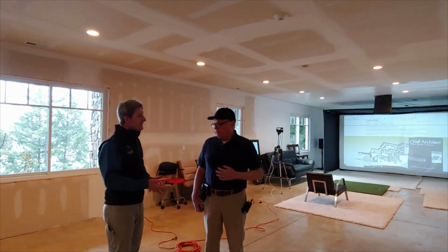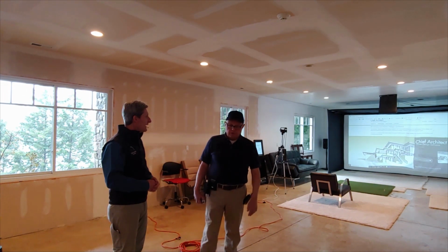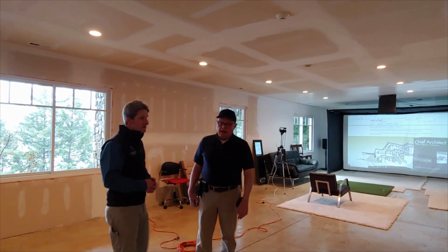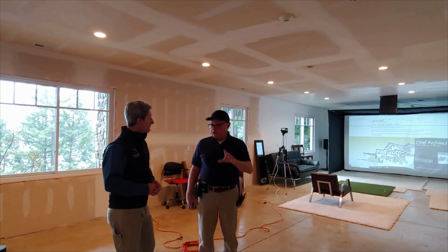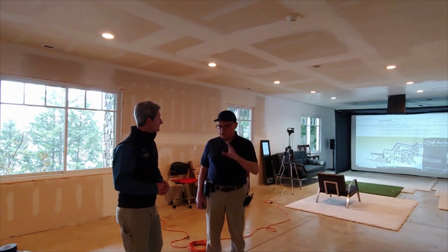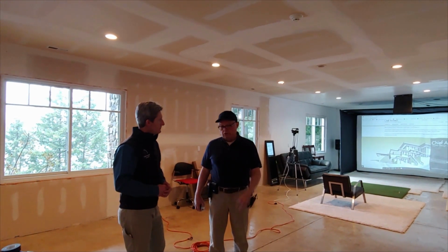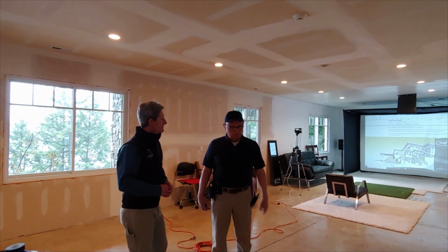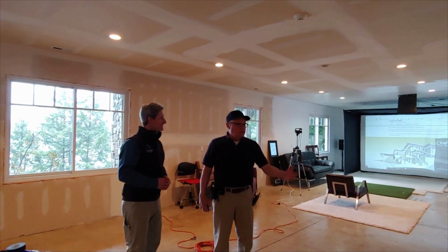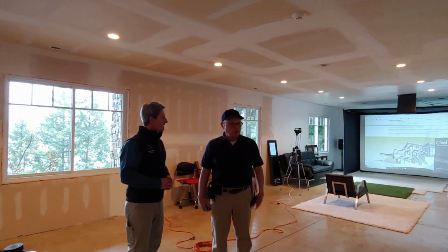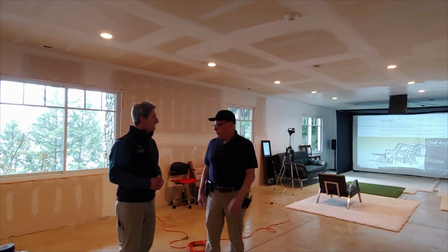That'd be easy to do if you put the switches in, run your dimensions, and then it could be laid out when the guys come in and nail up the walls. A lot of times it's not really necessary to run dimensions on the switches, as a general location is good enough. If I get it within 6 inches or so, we're going to know that the switch or plugs are on studs. And in this particular instance where the room isn't finished, we can clearly see where those studs are. So, a little easier.